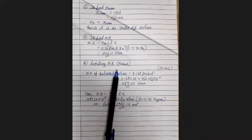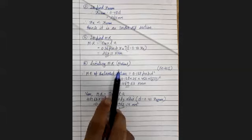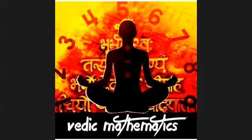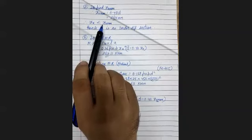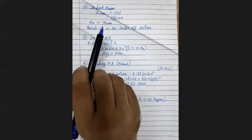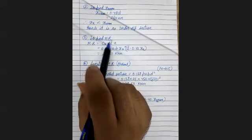You will calculate Tu into lever arm, right? No. Redesign. While calculating, the balanced MR will remain the same, sir. Exactly. X is equal to Xu max. Perfect. So when Xu is greater than Xu max, you will consider Xu equal to Xu max, and then you will find out the MR. So that is nothing but your balanced MR.